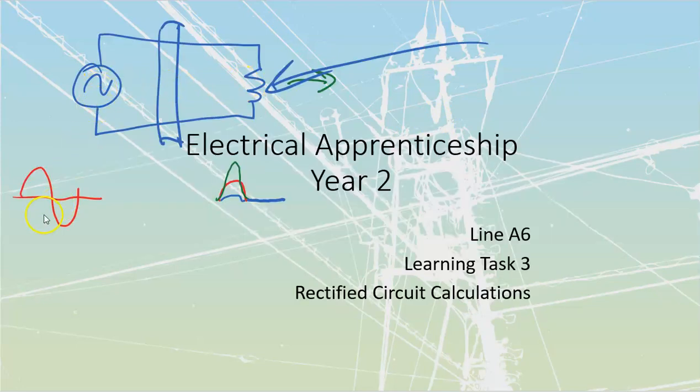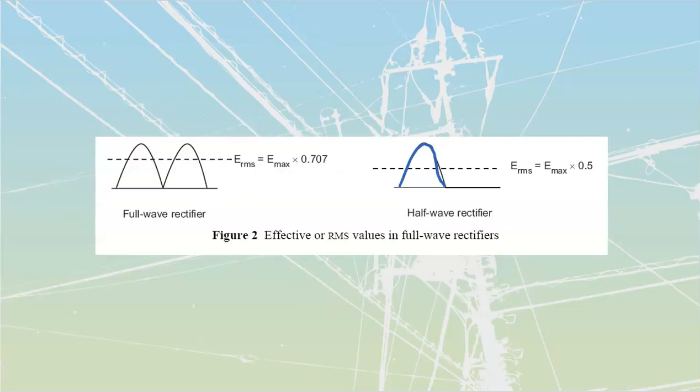Remember what we talked about: if this is going to be full wave, we take all of the voltage and put it over top, and as a result all of the current is going to follow that, and therefore all of our power is going to look like that. That is the exact same power that I would have out of a circuit if I had an AC circuit. I don't know if you remember this from the AC. We'll just draw it here. If I've got volts, I'm going to have in-phase current. If I multiply a positive times a positive, I get a power that looks like that. Then here I multiply a negative current times a negative voltage, and I get a power that's going to look like that. Poorly drawn because I'm no artist, but you see that it's the exact same power waveform from one side to the other.